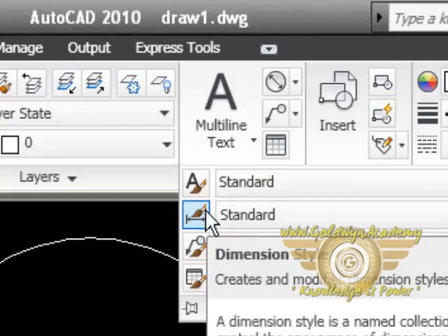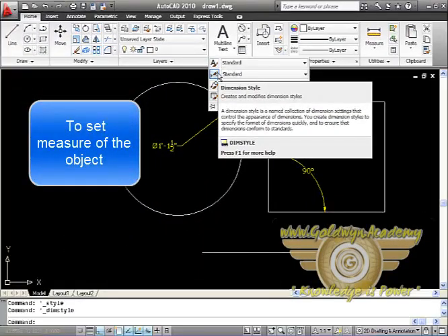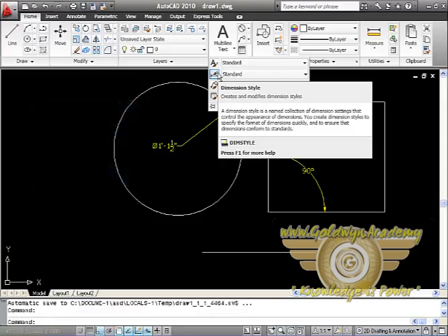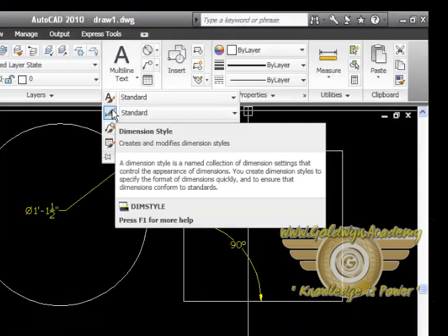A dimension is a line with arrows at each end drawn at the angle at which the dimension has been measured. The dimension text is situated along this line, sometimes dividing it into two lines. Usually, the dimension line is inside the measured area. Sometimes, however, it does not fit. In such cases, two short lines are drawn outside the measured area with arrows pointing inwards.